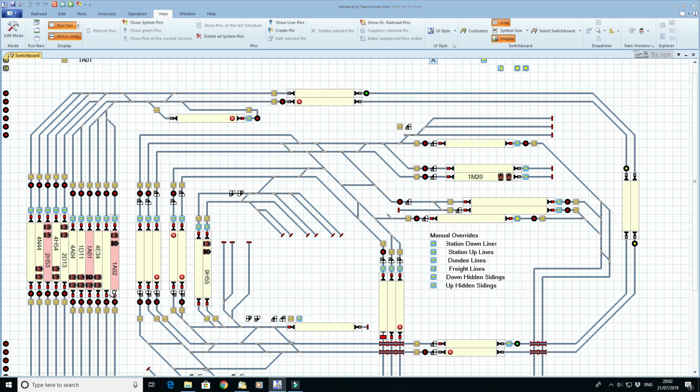At either end of each block are route setting buttons. To set up a route manually between blocks, I press the button at the exit end of one block and then press and hold the button on the next block or group of sidings. As well as setting up the route, the signal is cleared to the appropriate aspect. Signal main aspects are shown here in searchlight format, although the actual signals in the layout will be 3-aspect signals.